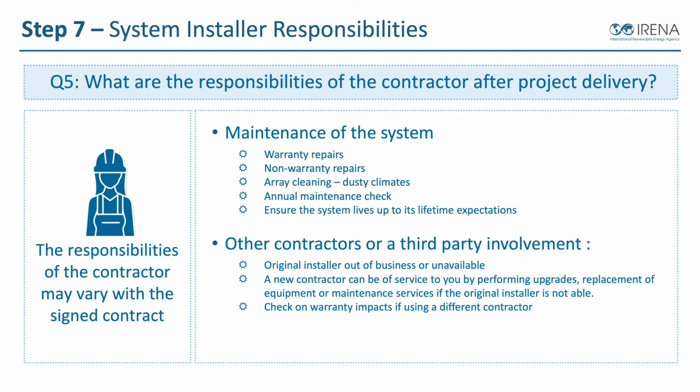and so it's not a warranty claim, and that needs to be replaced under a non-warranty repair. Array cleaning varies a lot based on region. If you're in a place that gets a lot of rain regularly, then most of the time we usually don't wash arrays. The rain usually does fine to keep them clean enough. If you're in a really dusty area, then sometimes array cleaning is part of a contract, either an installation contract or part of an ongoing maintenance contract. So check on that.